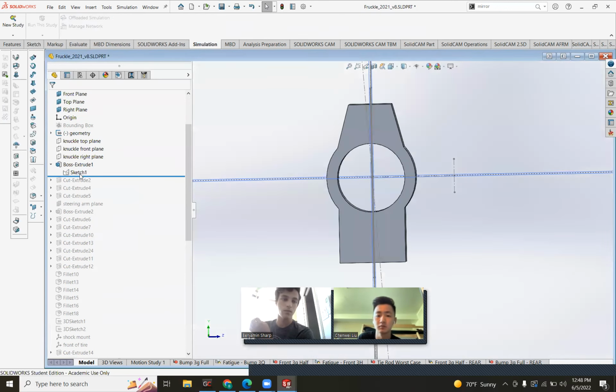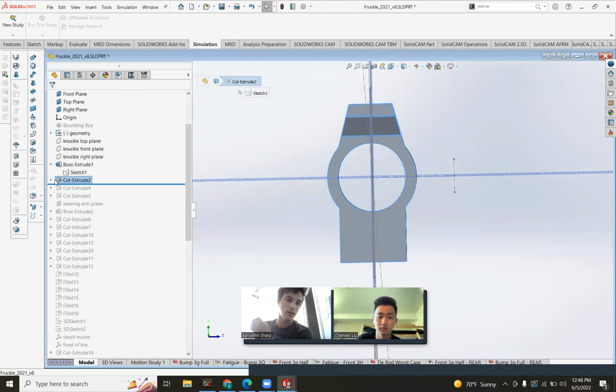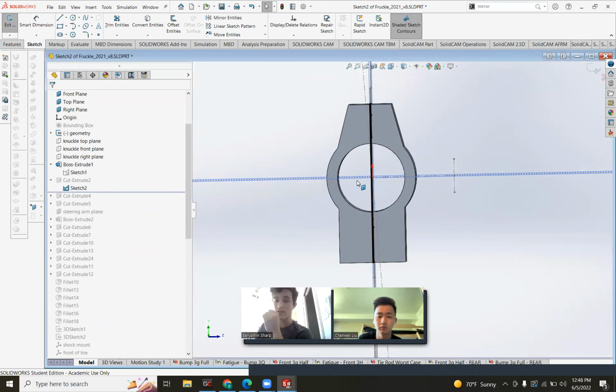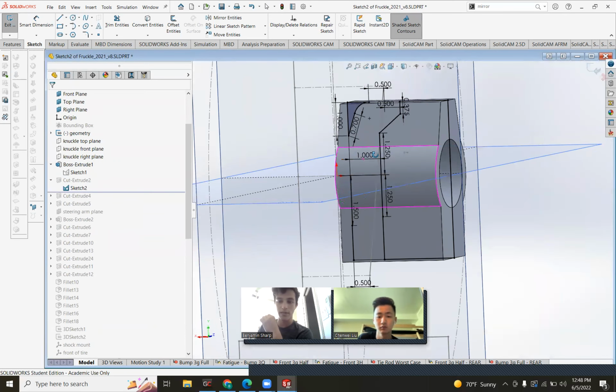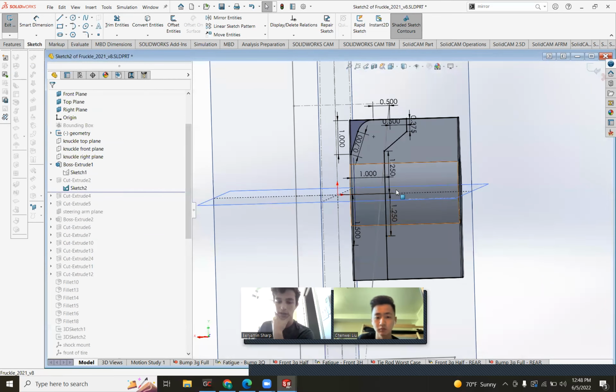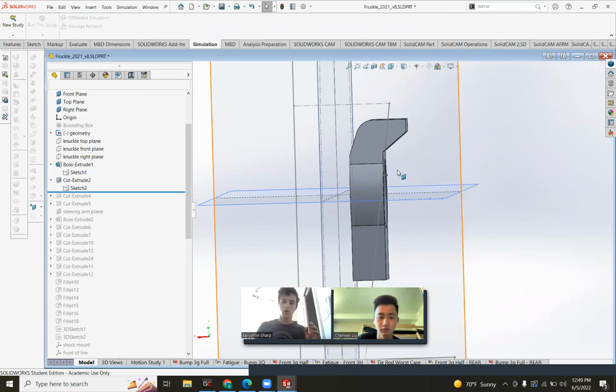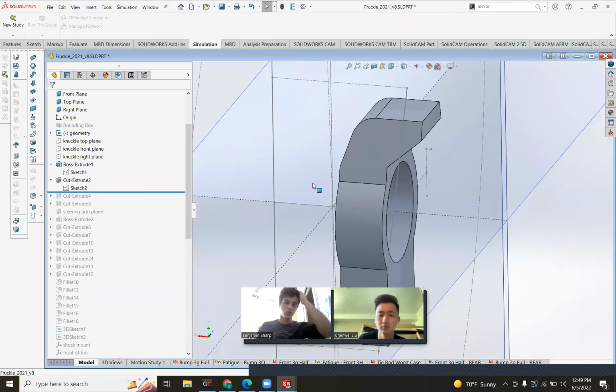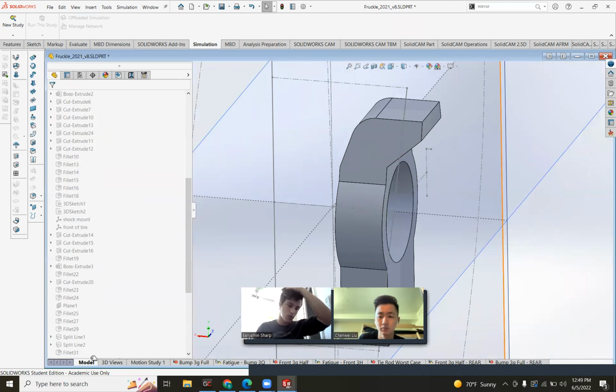Then once I had those pretty narrowed in, I started playing with these values. I always kept this thickness at 1 inch, but I messed around a lot with these up here until they were good and the stresses were good. And by stresses are good, I mean you see a lot of green. The stress is pretty constant. There's no corner that's too tight or edge that's too small or hole that's too close to an edge.